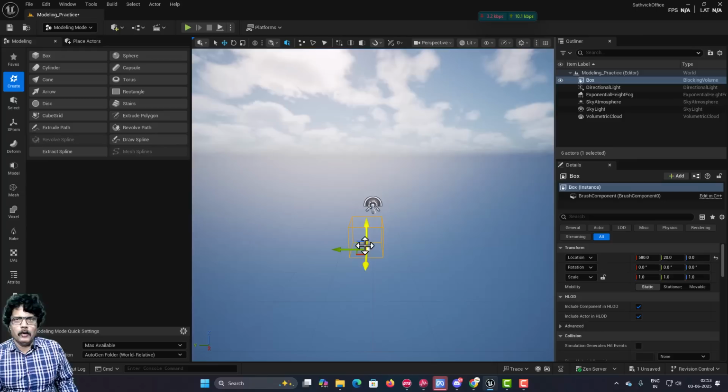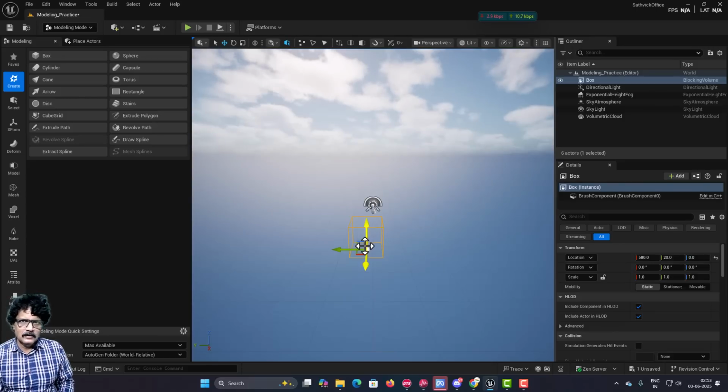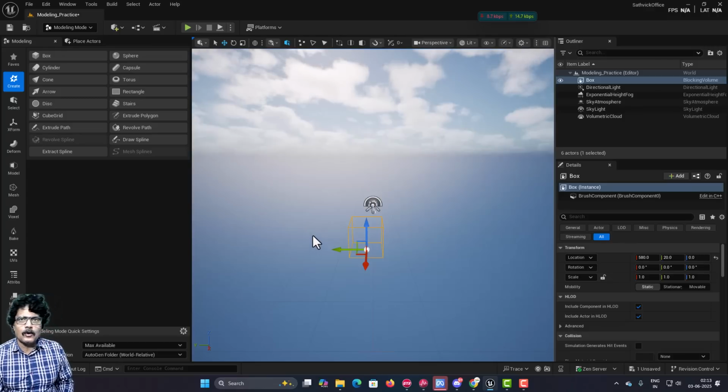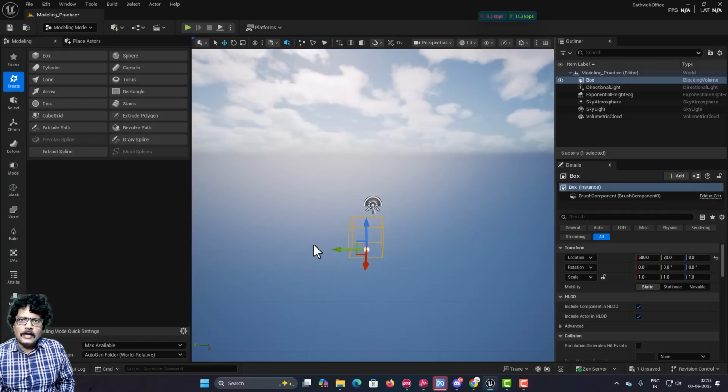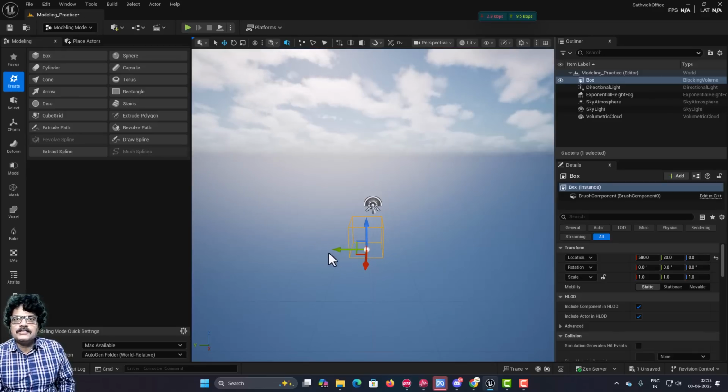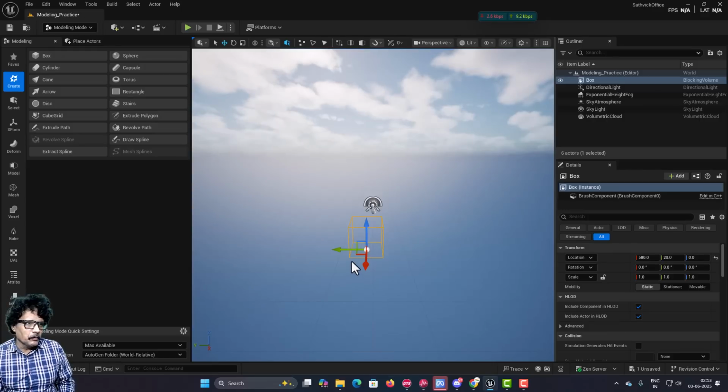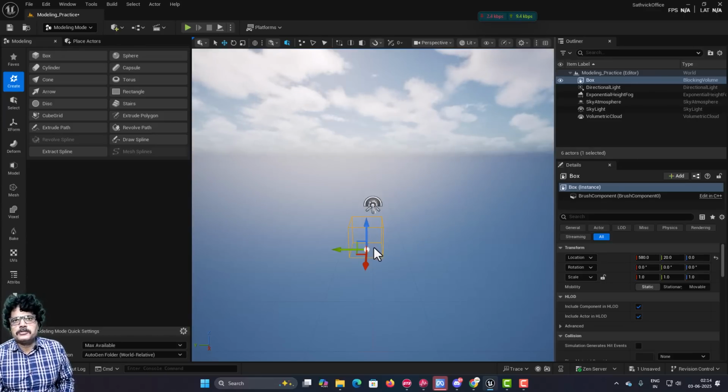It is a hidden model, and why do we use this hidden model? When we are working in this 3D environment, especially in a gaming environment, say you are building a game and a character is going to enter near a room, and as it comes near the room, the door should open. So, you need something to trigger the door opening, and here we can add this invisible volume and attach a blueprint to it, so that as soon as we move inside this volume, the door is going to open. These empty volumes are used in a lot of places during game development.